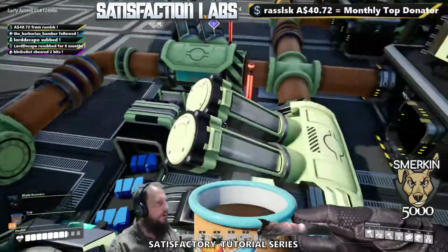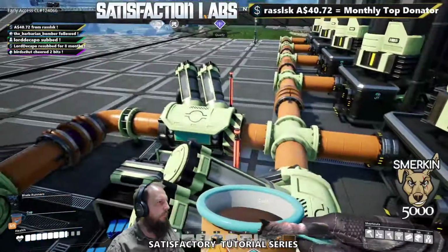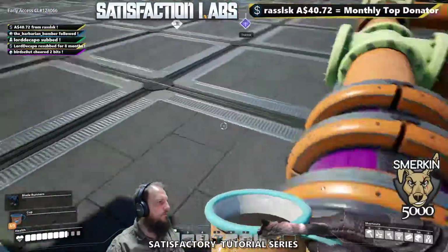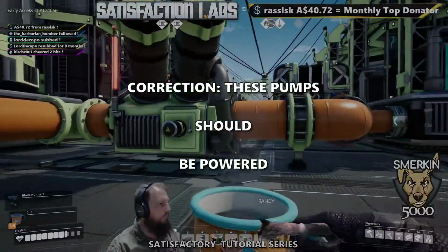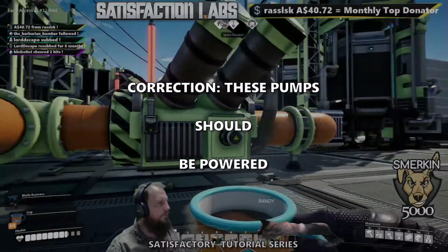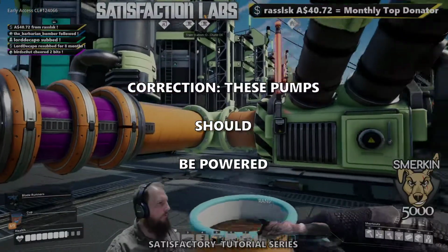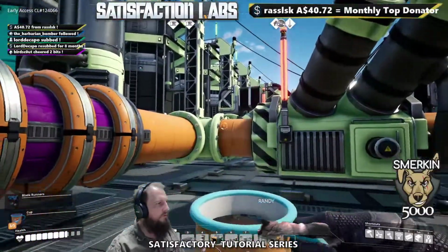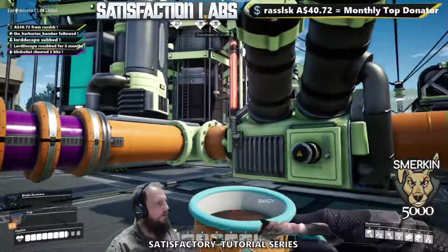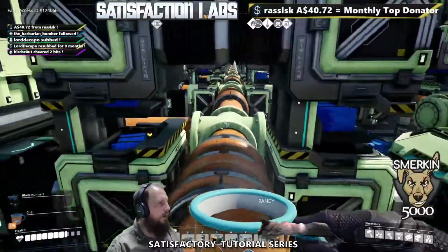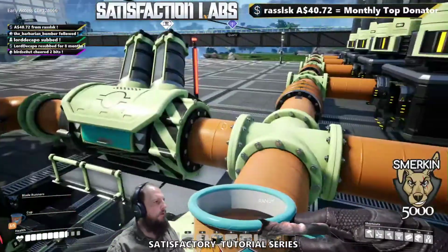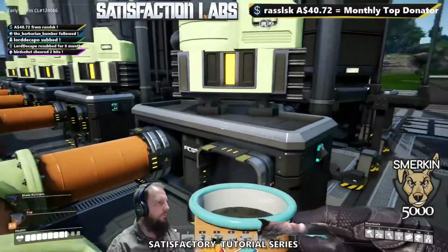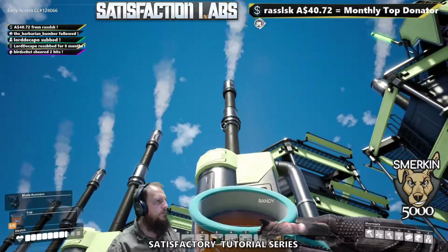But one thing here you'll notice, I've got some pipeline pumps. And you'll notice them, they're not powered on. They act as a valve, because this is the flow direction of the pump, and it prevents any backflow from these other machines flowing back this way. So once the product comes through these pipeline pumps, it will never feed backwards. It's just a little safety precaution, and helps maintain flow.